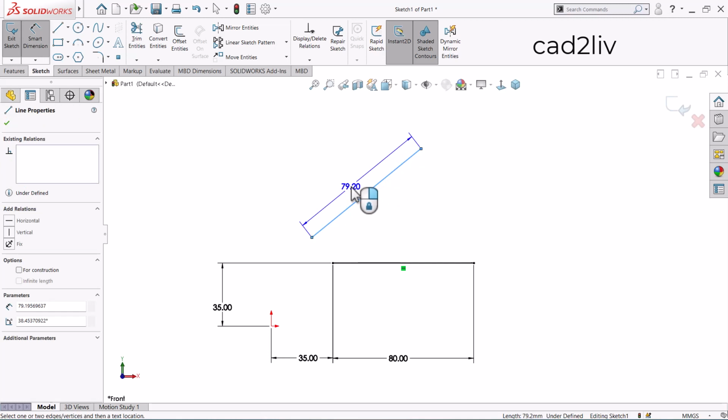Okay, now just hover the mouse without holding any kind of key. Now just drag it. Here comes the vertical dimension. Like for getting this dimension, you just have to hover your mouse without holding any key. Okay, and if I just put it here, so here comes the horizontal. In this way we can have the dimension in the three respects.